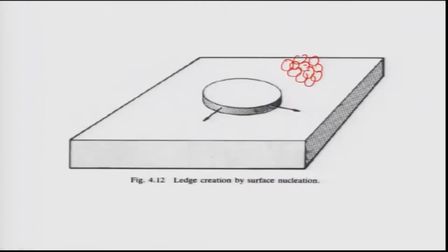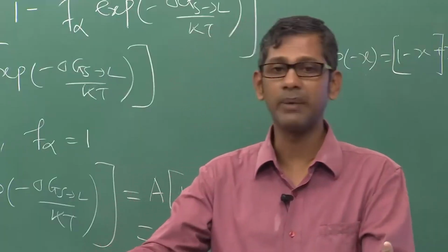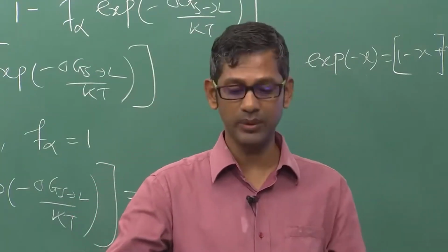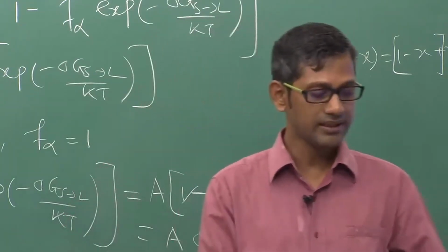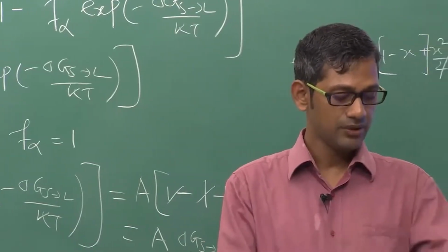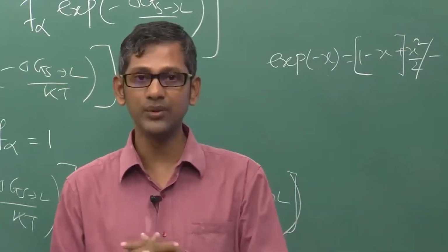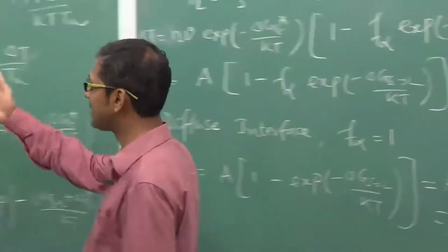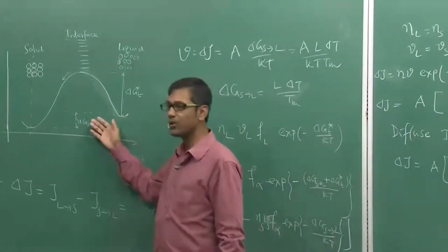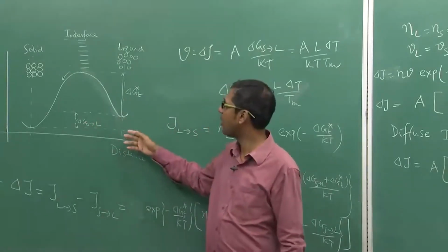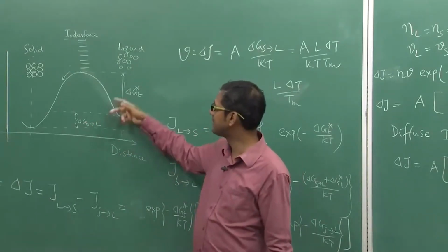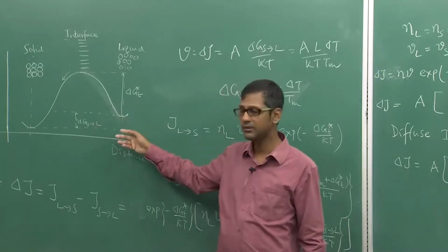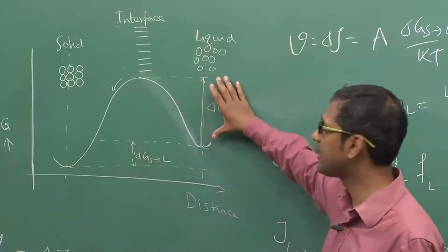Now, in the 4-5 minutes of time I have today, I'm going to tell you what can actually happen when I have a surface nucleation. Let us discuss that part. As you see, what we need to modify is this expression. This construction will remain the same in this case. The only thing that is going to change is this, which is basically the total energy difference between the solid and liquid of the atoms.